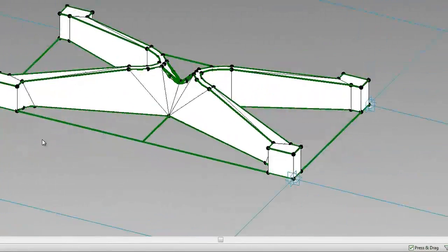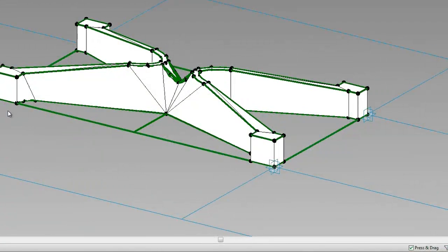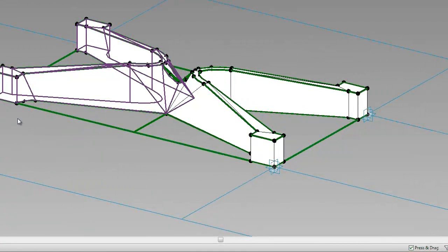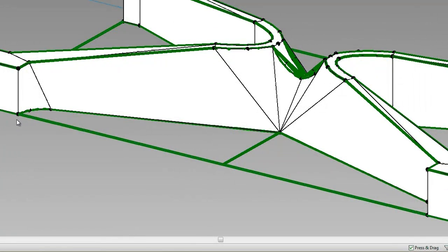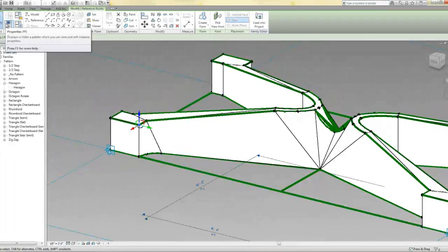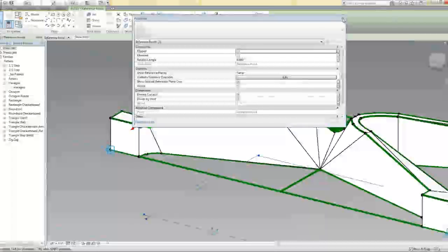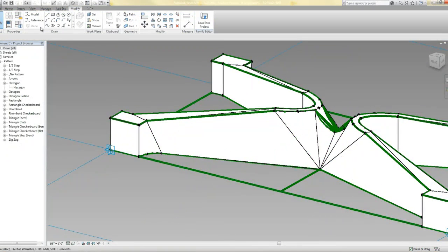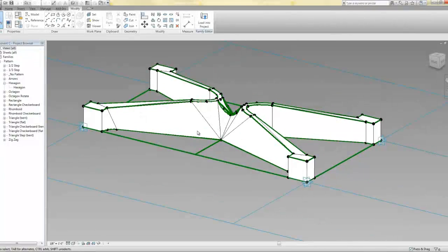And you can see that the predominant tool for controlling this is lots of control points building up these relationships. The main mechanism controlling this, if we select a point and go into its properties, is offsets, which are just specified distances in a plane away from a point. So that's how most of this geometry is controlled, and then there are these rail curves built in between it.